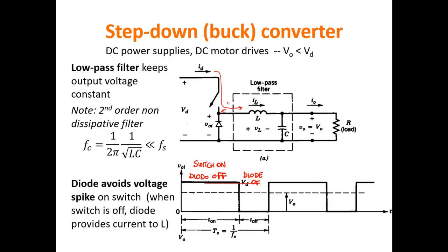But if the diode is present, when the voltage goes down to minus V gamma, which is the voltage at which the diode is turned on, then the voltage can stop here because the current in the inductor can finally come from the diode. So the presence of the diode basically ensures that the voltage on this node does not go to a smaller voltage than minus V gamma.